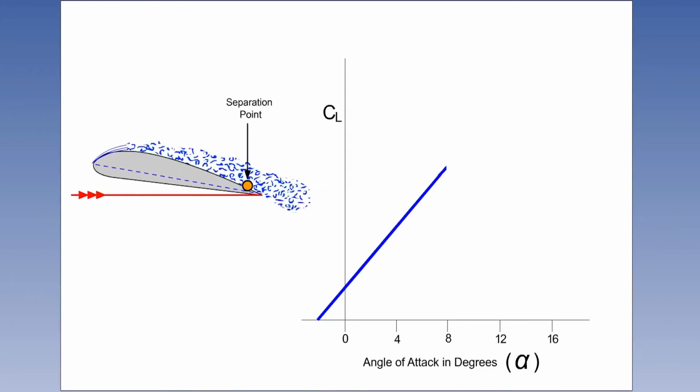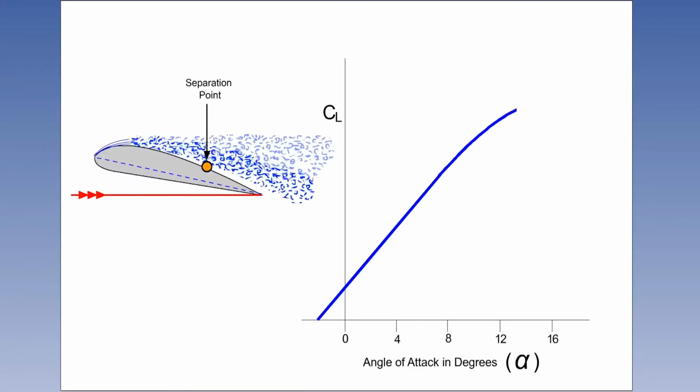The stall, then, is caused by airflow separation, which occurs either when the boundary layer has insufficient energy or the adverse pressure gradient becomes too great. If we look at a sequence of an approach to the stall, we can see that at low angles of attack, virtually no flow separation occurs before the trailing edge, the flow being attached over the rear part of the wing in the form of a turbulent boundary layer. As angle of attack, or alpha, is increased, the adverse pressure gradient increases, reducing the kinetic energy, and the boundary layer will begin to separate from the surface at the trailing edge.